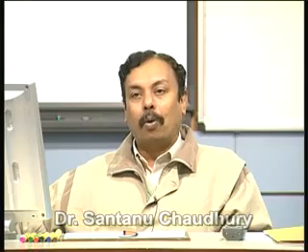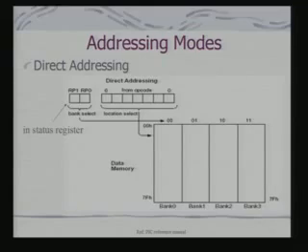Now, let us look at addressing modes. What is addressing mode? We use addressing modes for specifying operands in an instruction. PIC supports direct addressing, indirect addressing, as well as immediate mode addressing. We have already seen the structure of instructions which support immediate mode addressing. Now, let us see how direct addressing is supported in PIC.